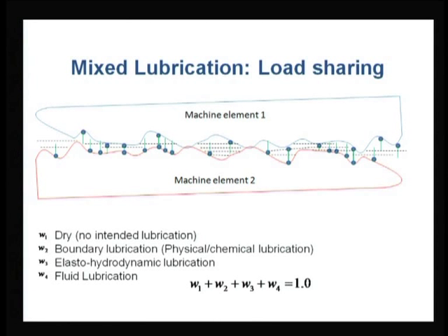So it depends on which characteristics we want. If we want high lubrication, or a high coefficient of friction but lesser wear rate, naturally we will keep a high relative velocity and a thick viscous fluid. So the two surfaces are completely separated, but it can give a high coefficient of friction.